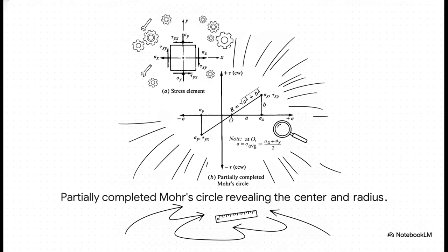But here is the absolute magic of this method. That radius is mathematically equal to the maximum shear stress. You get the answer instantly. No complex algebra needed, just basic, straightforward geometry.